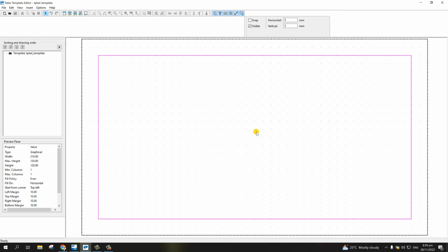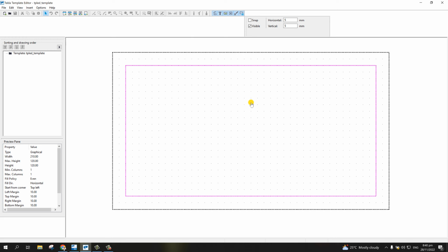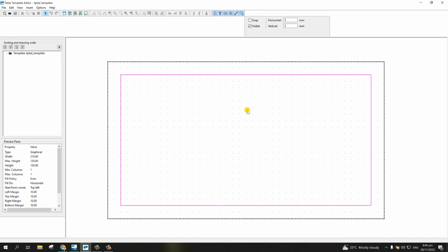In my previous video, I have already discussed some topics regarding the textual template and graphical template. So you can revisit the previous video that I have created or the training videos for the templates. But this time around, I'm going to discuss how to create the template that will open up a PDF. So again, when you create a new template, instead of creating a new textual template, we're going to select a graphical template. So graphical template is usually used in our DWG file or drawing title block.